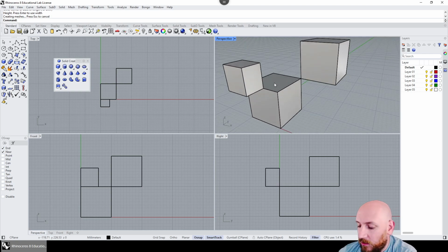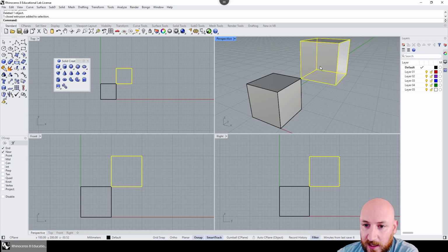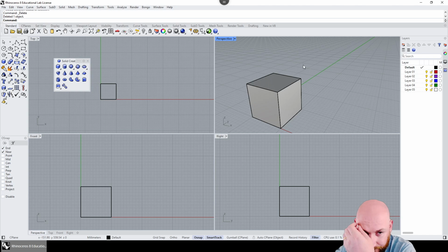Turning these snaps on and off to make sure you're precise is really, really important. It's one of the problems of young designers: when you zoom in on the drawings, nothing is actually accurately on top of something else. So the corner actually has like 20 very close, but not exactly snapped lines. That's not a great way of drawing and can create a whole bunch of problems when exporting, depending on what you're exporting for.